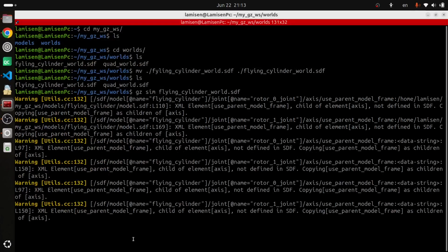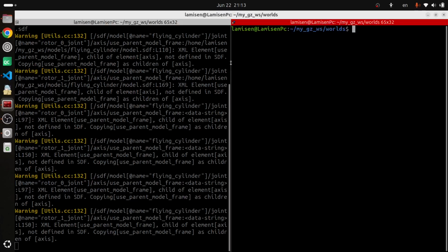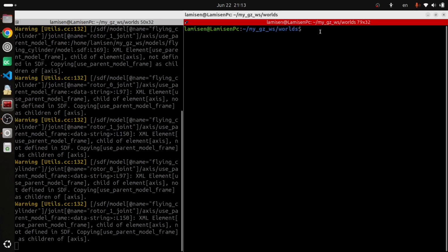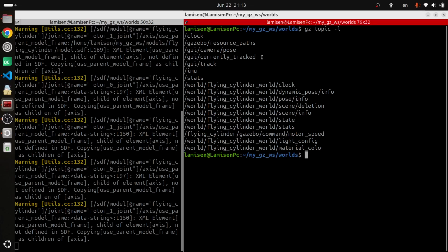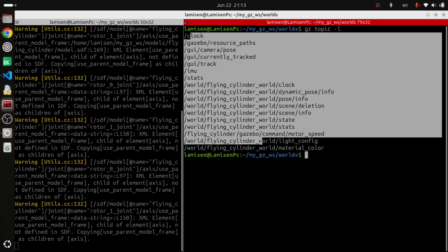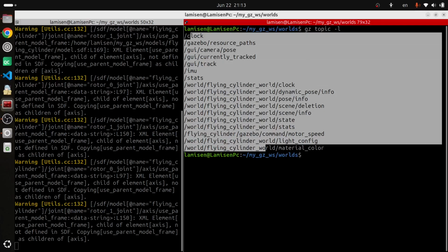Let's go on with the topics. Let me split the terminal here, to work with our topics. To see the list of topics being published, you should enter gz topic -l for list. Then hit enter. These are the topics that Gazebo is publishing right now.